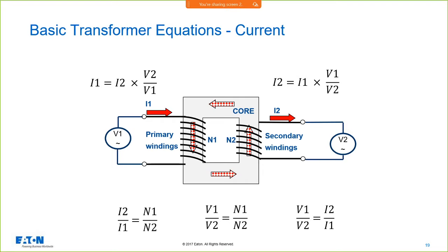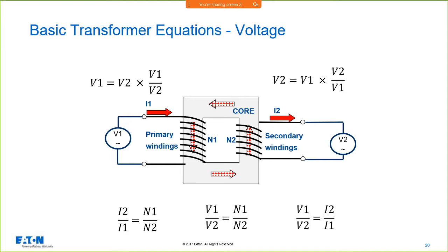But if I have a reverse power feed, where my primary and secondary are converse because I'm stepping up instead of stepping down, again, it just follows that basic principle. The higher voltage will have a lower current than the lower voltage, because it's the same amount of energy that you're transmitting. And then I can do my voltage as well.